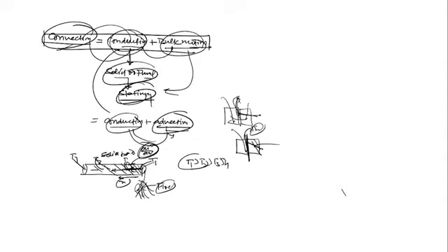Whatever energy has been generated in between, at this position, that energy gets transferred from this wall of the solid to the other wall of the solid. Due to what? Because this wall is at high temperature. Wherever you have rubbed directly, at the center, the temperature is higher and here the temperature is lower. T1 and T2 are different temperatures. That causes a temperature gradient.